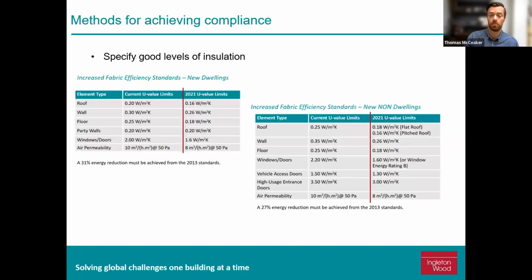Insulation is also important here. We always think about insulation in the winter, we're trying to keep the heat in, but it also works the other way around. In its most basic form, insulation just reduces the flow of heat from one area to another. So if it's hot outside, it doesn't get quite so hot inside if you have a good thermal shell to your building. By using high levels of insulation, we can manage that temperature better. We can decrease heating loads, and the external conditions don't translate quite so well.